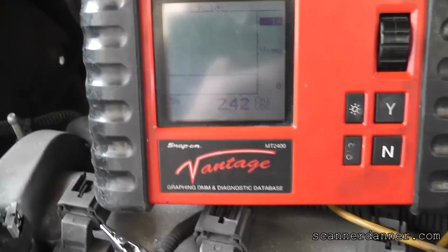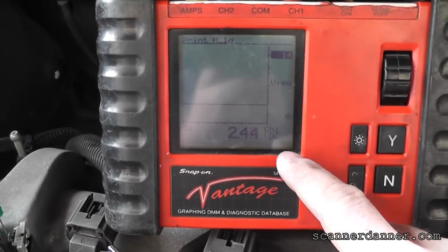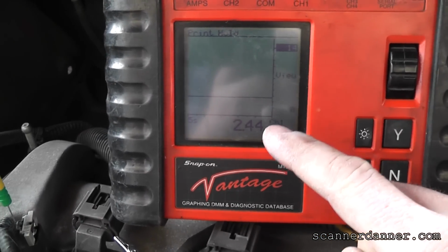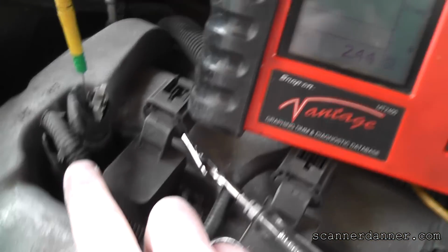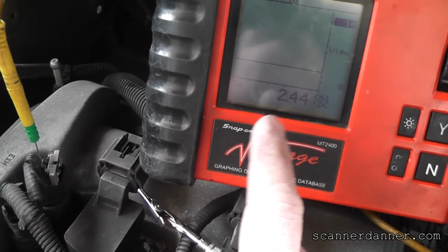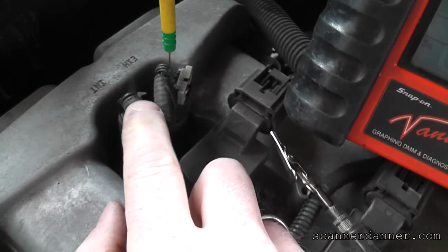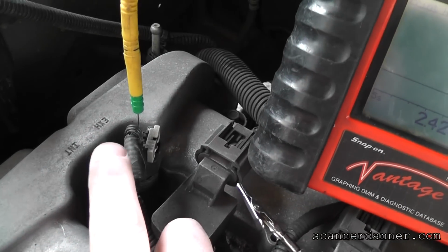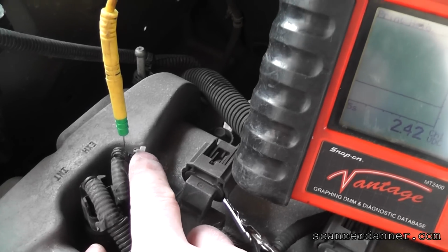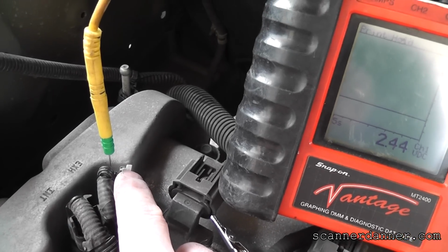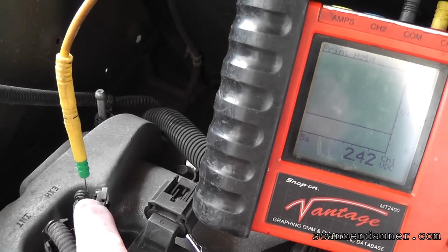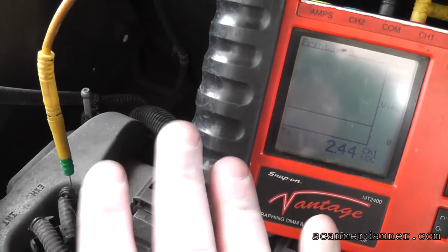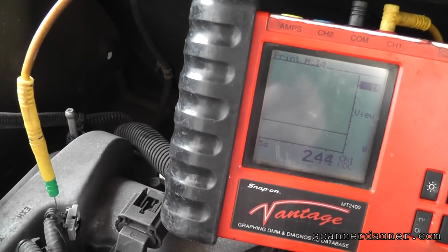All right, so this 2.4 volts, I think we can call this a bias. I don't know why the bias changed. It was within me activating the intake side. I came back to the exhaust side and this changed. You saw when I did the intake side, unplugging it, that 0.93 showed up, same as I had when I started here, telling me I have an open in the circuit. Ground was good. If the ground was bad, voltage would have been high. It was not open solenoid. We're not deviating from that.